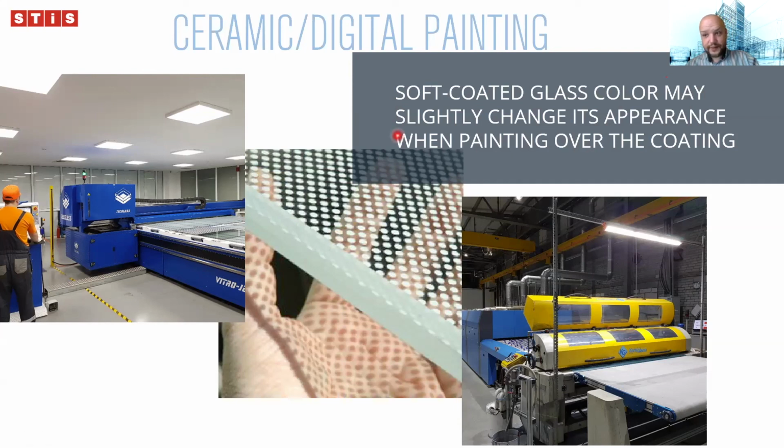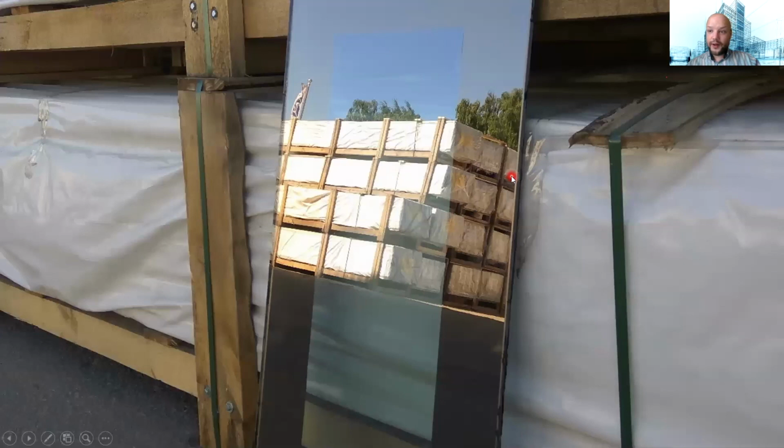For a processor, this is quite a disaster, because in this case the tempering furnace has to be stopped for several days and cleaned up. And also the ceramic rollers, which are quite expensive, can be damaged. That's the first thing. The second thing you need to remember is that if you apply paint directly on the coating, the coating may change color a little bit, go goldish, for example, as you can see in the photo.